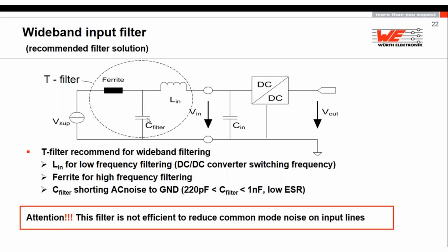But for this ferrite bead, you should not use the super duper 2.2 kilo ohm one, the most powerful, or 2.7 kilo ohm. It makes no sense. All these 2 kilo ohm ferrites have a peak of 2 kilo ohm, but because the multilayer has many layers inside, it will not have a nice bandwidth. Additionally, all the ferrites are measured in a 50 ohm system impedance. We don't have 50 ohm system impedance at a DC-DC converter. We may have something between 10 and 20 ohm system impedance.